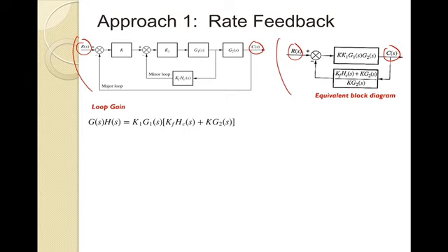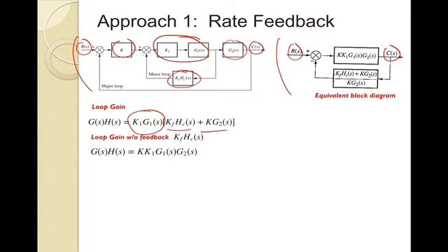If we look at the loop gain of that, you'll see the loop gain here, our G(s) term, and you'll see it as written there. It has common parts here, K1 and G1, which you could think of as right in the center. And then I have this feedback term, this G2 K-feedback term as well, those added, and then that combined is multiplied with the plant K1, G1 term. So that would be the loop gain.